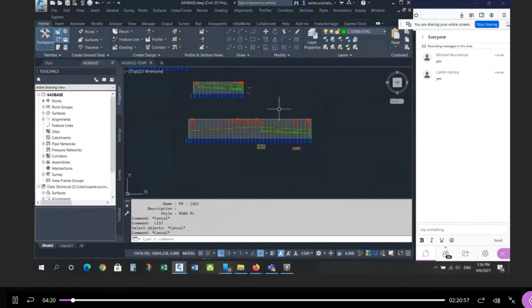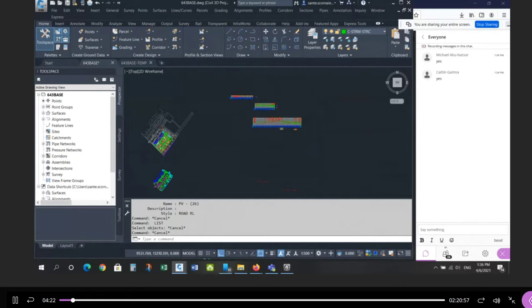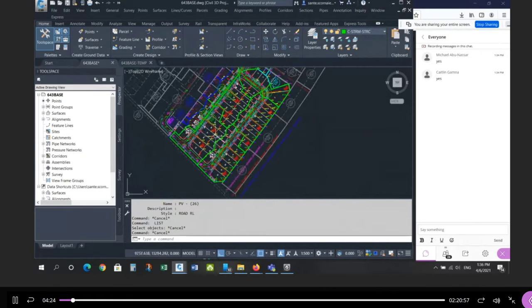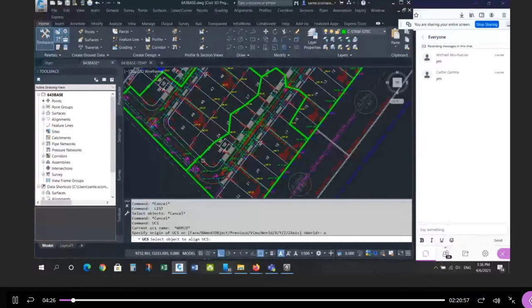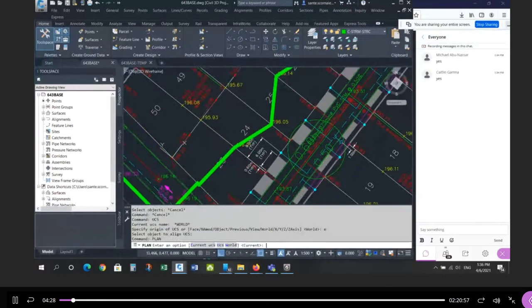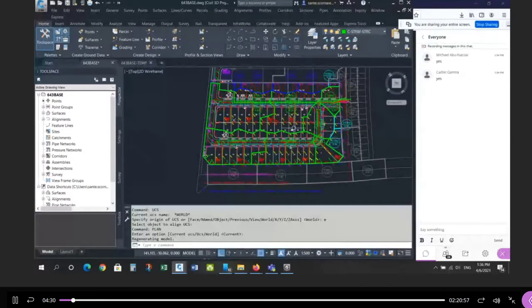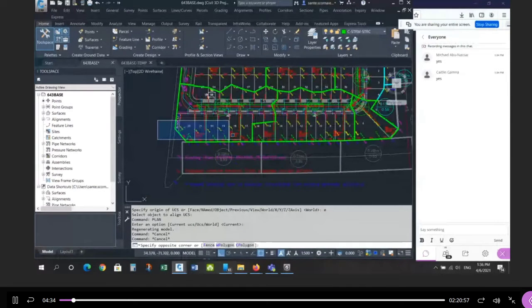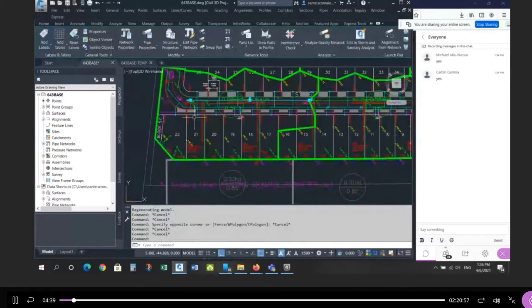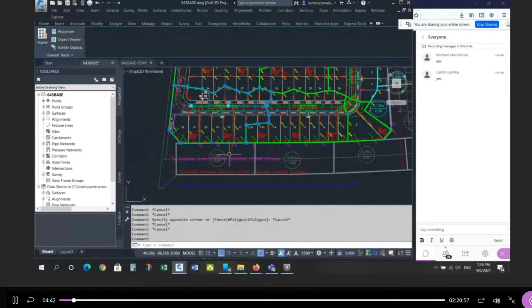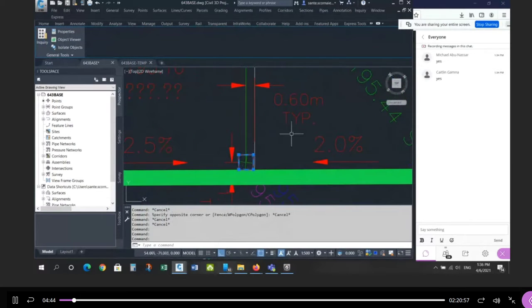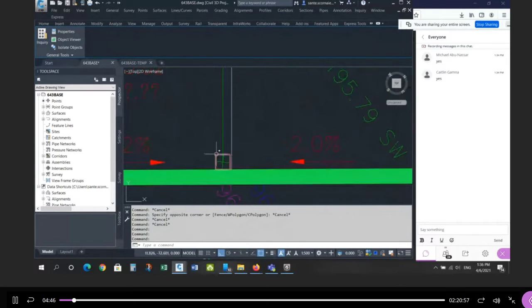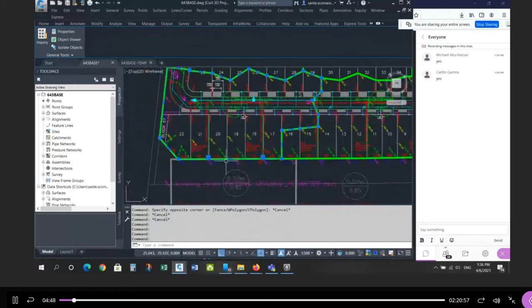Okay, just a quick housekeeping thing. So if you've designed all of the, let's take a quick look here. Here's the revision. So we did one revision so far. Let's look at the next one. So the first thing I did was once we had all our drainage areas, I added these backyards now to the mix, right? So to design this street pipe, I have this total area, which is this rear lot catch basin and this rear lot catch basin.